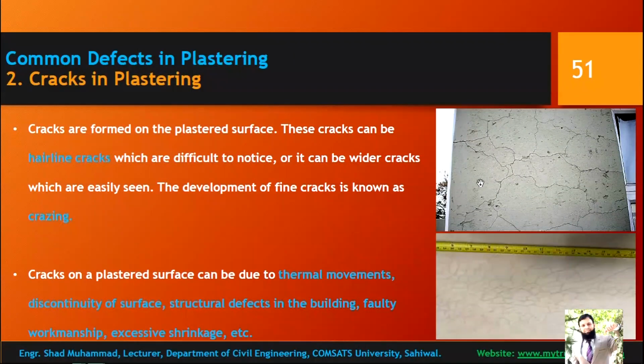You should be aware that these cracks are not dangerous cracks. These are not structural cracks. If there is a load bearing wall, even then these are not a thing to be worried about. These are surface cracks, not structural internal cracks.